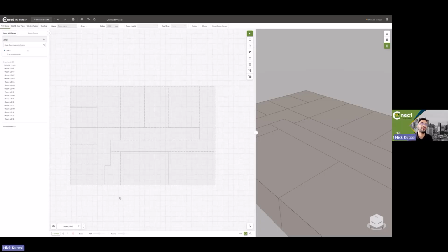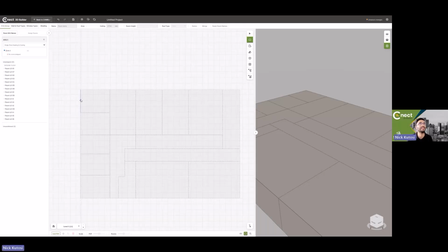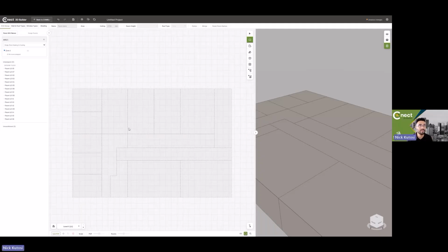And you can see here that we've got a ghost layer of the rooms below, and that's so that we can clearly or easily line up our building, particularly the envelope, so we don't get sort of a Jenga tower. Make sure that envelope is clearly aligned, and so as you're drawing the rooms here, it'll snap to the floor below as well. Of course, we also want to add in our PDF background, so we'll go ahead and do